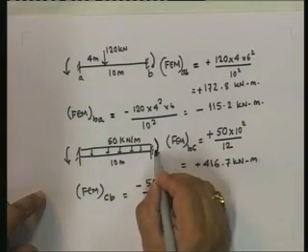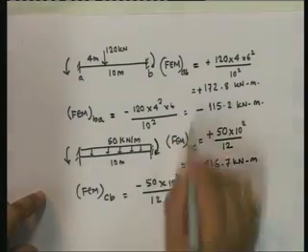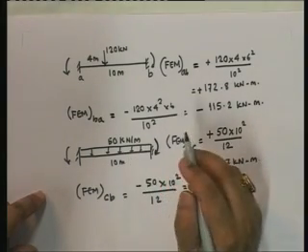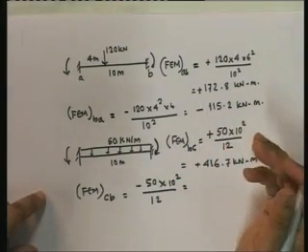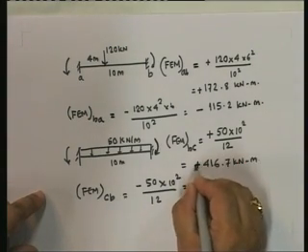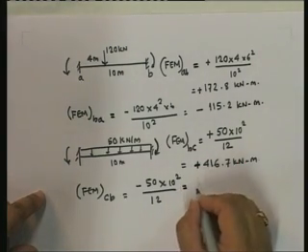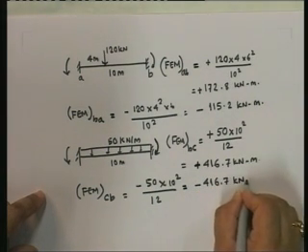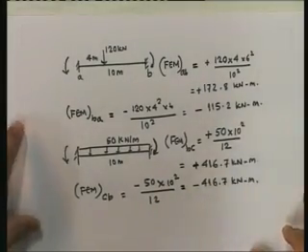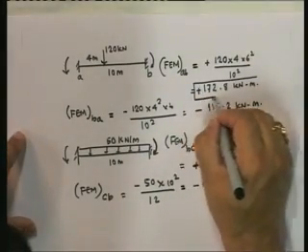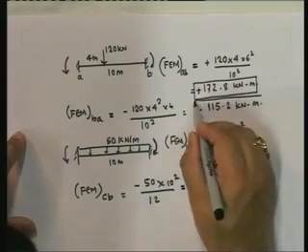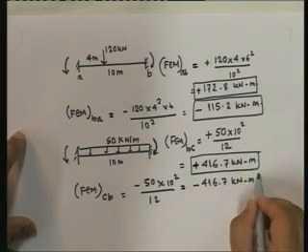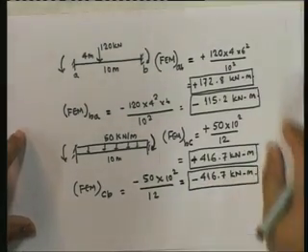Minus because I am assuming anti-clockwise to be positive. Please note that. That is my sign convention, that I assume anti-clockwise to be positive. Others may choose clockwise as positive. There are various ways of solving this problem, but understand that as long as you use one particular method, you have to be consistent. You cannot keep changing your values. So this is my fixed end moment AB. This is my fixed end moment at BA. This is my fixed end moment at BC. And this is my fixed end moment at CB.